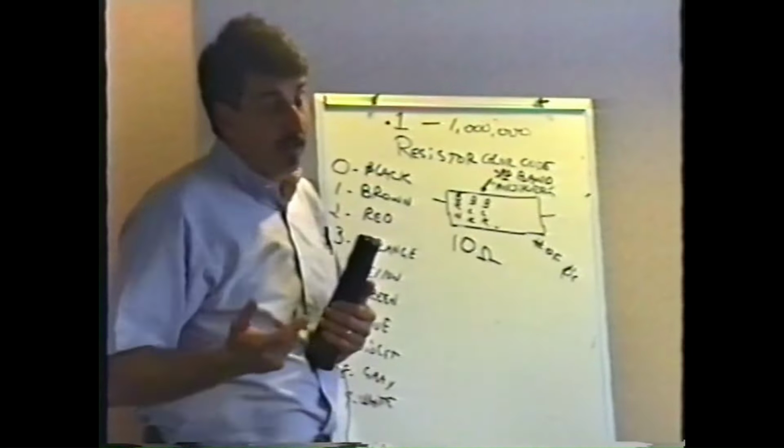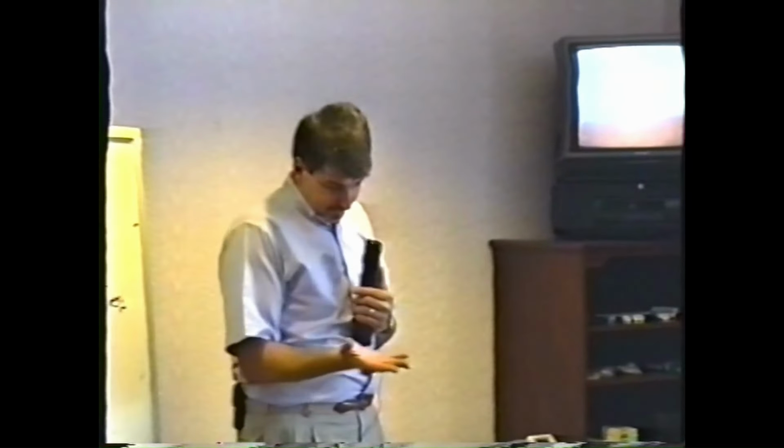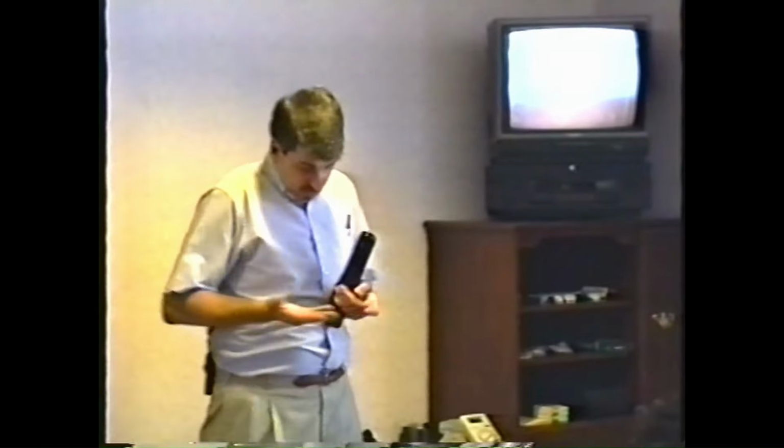So here's why I point this out to you, and this is really important. It has to do with the way things fail. When a resistor fails, it always open circuits. It goes way up in resistance. When a resistor fails, it never goes down in resistance. In fact, the only time you would ever see a resistor that was lower is if you look at the board and it's just a little chunk of carbon or charcoal sitting on the board, obviously all flamed out, in which case you'd find it by looking at it, wouldn't you?